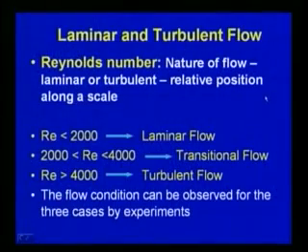But as far as the laminar flow condition is concerned, the velocity is small, so the flow moves as a layered flow, and there is not much disturbance in the pipe. Reynolds, through his experiment, showed that using the Reynolds number we can classify whether the flow in the pipe is laminar or turbulent. So, the Reynolds number shows the nature of flow in the pipe.